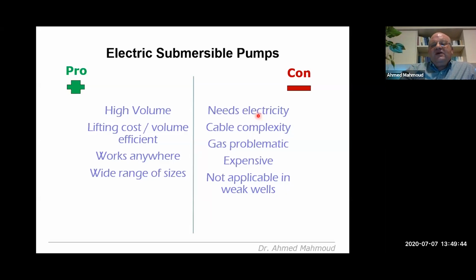But in more recent modifications, this problem has pretty much been overcome in the industry, and installation is now much smoother. Obviously it's gas problematic, very sensitive to a certain percent of gas. It's expensive, and maybe not that applicable in weak wells, because in weak wells maybe you don't have enough economics to justify the ESP.